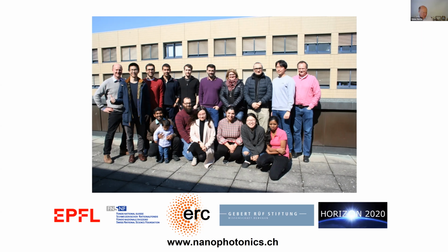This is, of course, a very important point which has been studied quite a lot. There are a few works from Steve Blair from Utah who studied that. So indeed, often you use a metal as adhesion layer, like chromium, and this can be detrimental to the optical properties. One must, however, keep in mind that it's very, very little. So you do a flash, and it's not going to make a continuous film. You deposit 2 nanometers, and it makes more islands of the material. And this indeed helps for the adhesion of gold on glass.